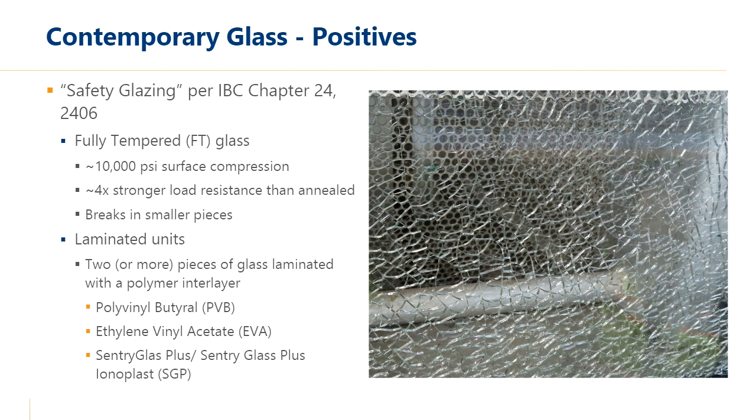Typical tempered glass goes through a heat treatment process where it is fed into a tempering oven on rollers. The oven heats the glass to a temperature of more than 600 degrees Celsius, and then it undergoes a rapid cooling procedure called quenching, which cools the outer surfaces of the glass much more quickly than the center. As the center of the glass cools, it tries to sort of pull back from the outer surfaces, and as a result, the center remains in tension and the outer surfaces go into compression. It gives it a strength of about 4 times that of annealed glass.